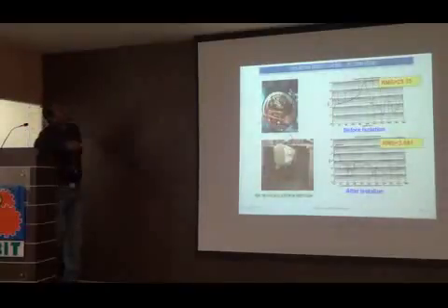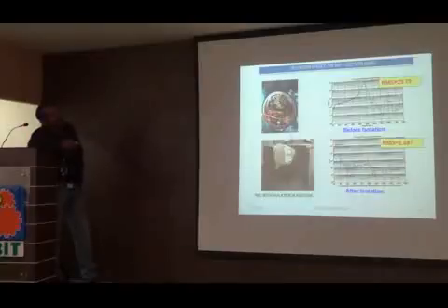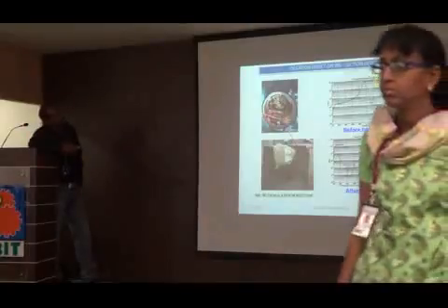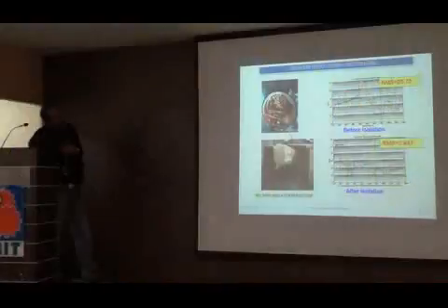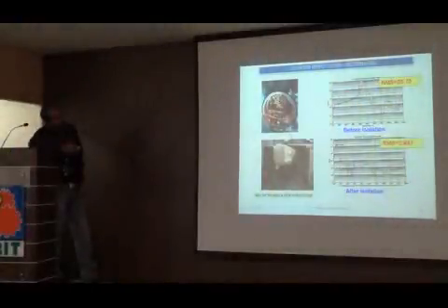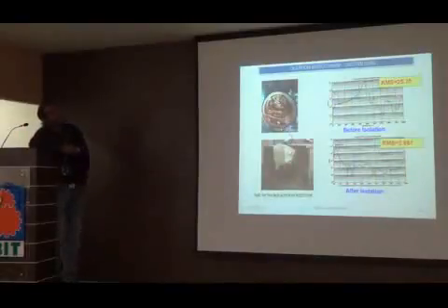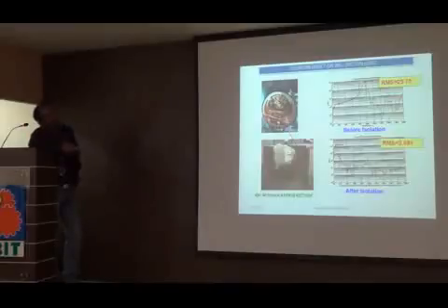Some cases where we have used an isolator: for example, another kind of system where we were getting very high input. So we needed to reduce the input, and we made some kind of isolation. Before, this was 25, and it has become 2.8. But if you see the frequency, the isolated frequency has become very low. So you can see it is like a low pass filter. Beyond this frequency, beyond root 2, it cuts off every energy that is given into the system. So this is the advantage. But one should also be careful about this peak.